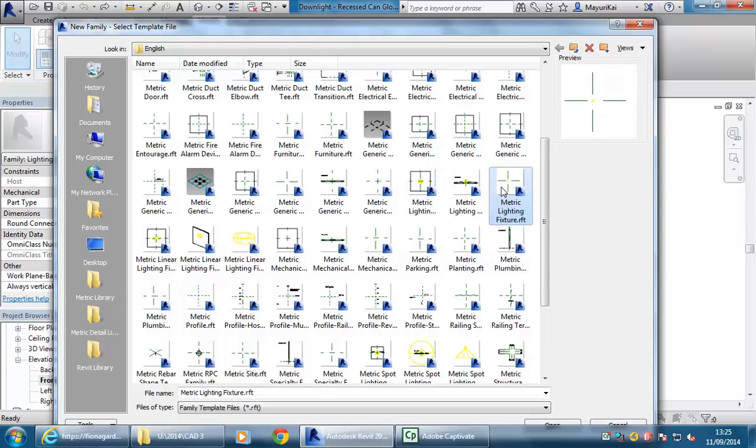And wall based you have there. And so they're hosted by different elements. They have to be attached to either a ceiling or a wall. But this one isn't hosted. So it just gives you a light that you can have as a floating light. And if you want to have something that isn't hosted, you can always make your own, we'll start with this template, and then you can just set them to any height and position you like.